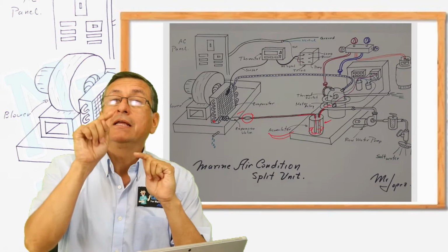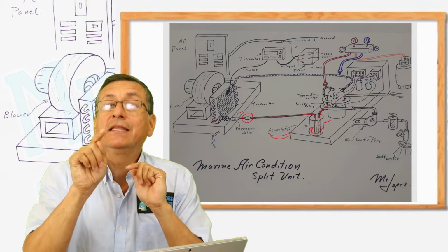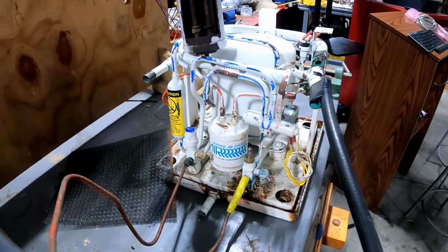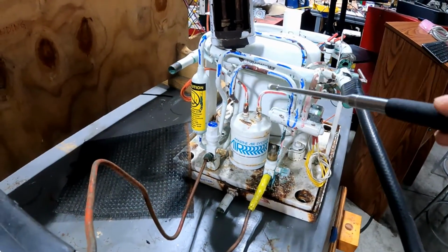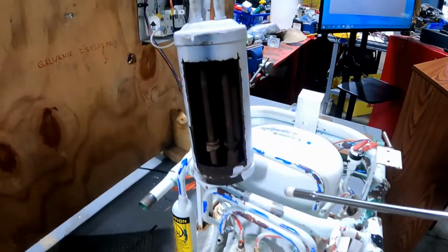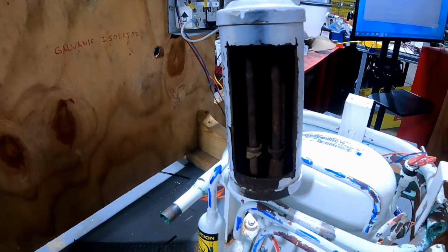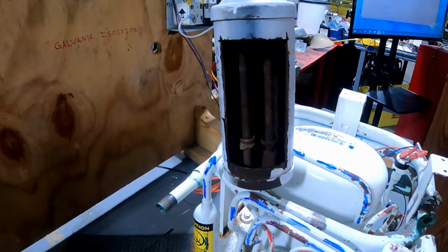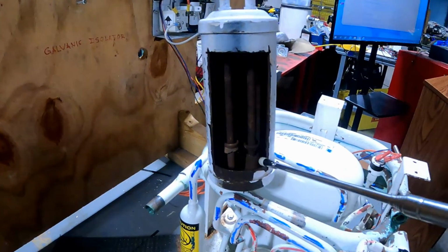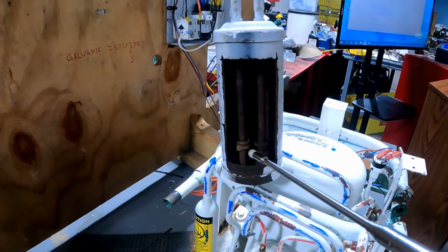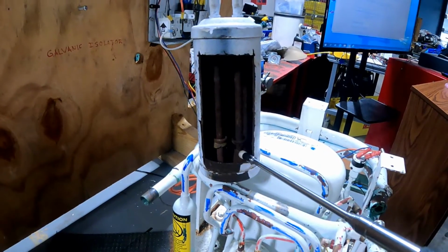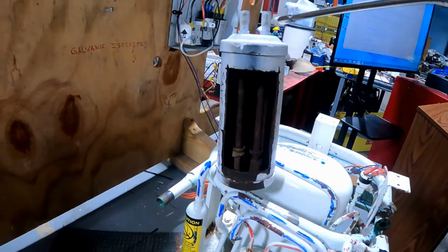Now we are going to check the receiver and the capillary pipes. Another important element in the refrigeration cycle is the receiver dryer. This is the receiver dryer. This is a section of the dryer. The refrigerant at high pressure and high temperature enters over there. This pipe in the bottom is open, and normally in the bottom of this container there is a hygroscopic substance to absorb moisture, to absorb humidity. After that, the refrigerant continues.